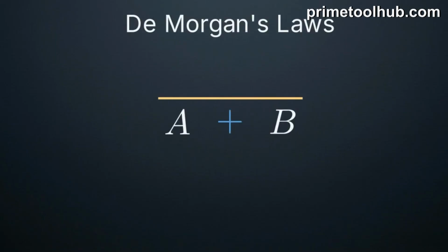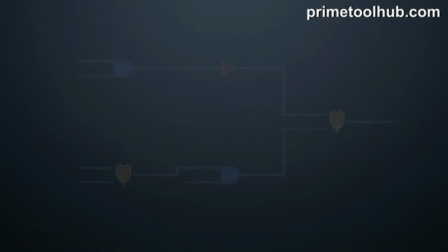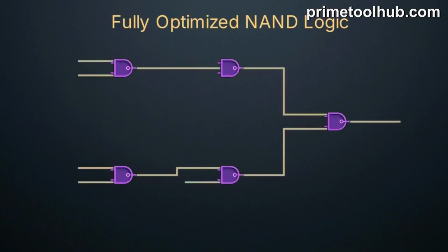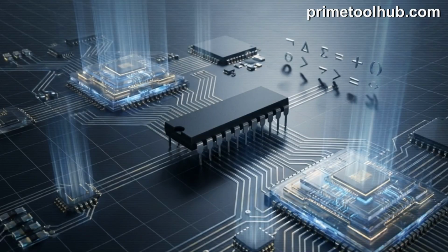The tool's engine automatically applies De Morgan's laws to instantly convert any complex mixed-gate Boolean expression. De Morgan's laws are mathematical theorems used to break solid bars and change logical signs without altering the final truth table output. This invisible mathematical conversion creates a highly optimized logical path consisting exclusively of NAND or NOR operators. By mathematically forcing all logic into this universal gate architecture, designers can standardize their manufacturing process and drastically drive down the cost of physical hardware.